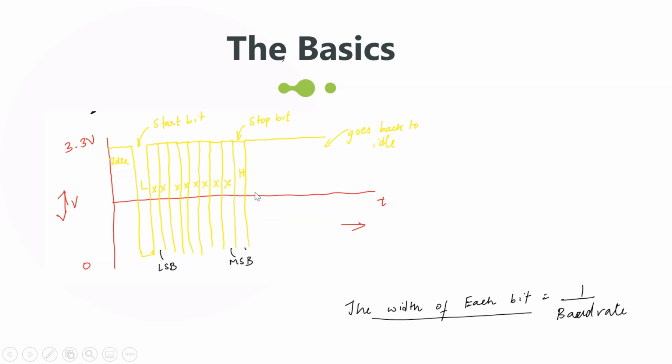A start bit usually initiates the serial bit stream, and a stop bit, or sometimes 2 bits, completes the data word. The UART also has an option of adding a parity bit to the stream to assist in detecting if a bit error has occurred during transmission.